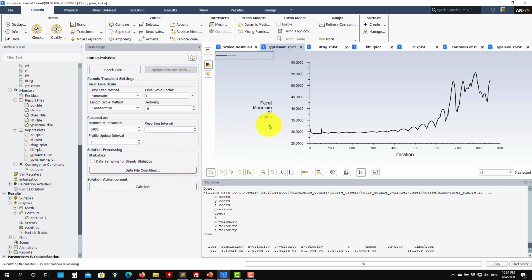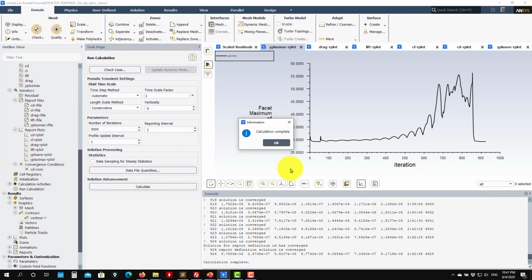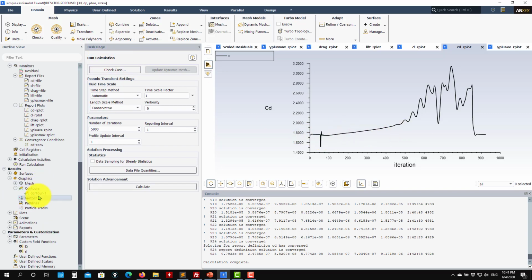Let's wait a little bit to see what happened here. In our case, it arrived at convergence in a few iterations. So see what happened for a highly unsteady state. Look at that, the couple solver damps everything really fast. Let me go here, and then we get again the steady solution. So this is the main difference.